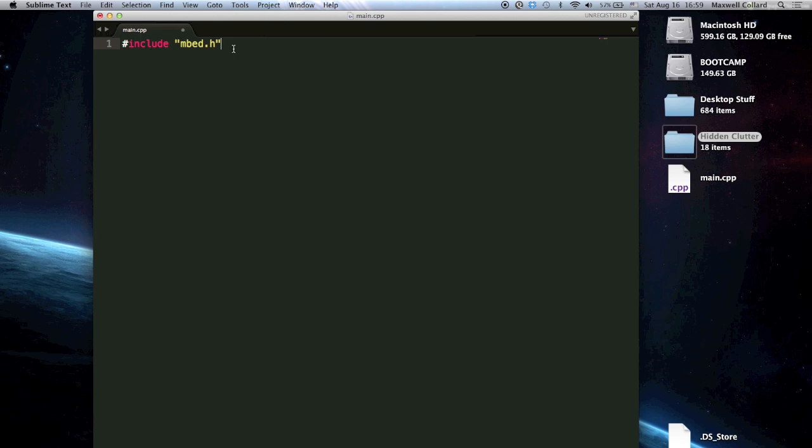You're probably going to want to include this in every one of your program files because it's essential to doing everything with the mBed microcontrollers. The next thing we're going to do is declare and define a DigitalOut object, which is of type DigitalOut. This is a class defined by mBed that lets you really easily control the digital output pins on the mBed board. For example, you can drive them high or low, or you can read whether they are high or low. So this gives you a way of interfacing with other digital things.